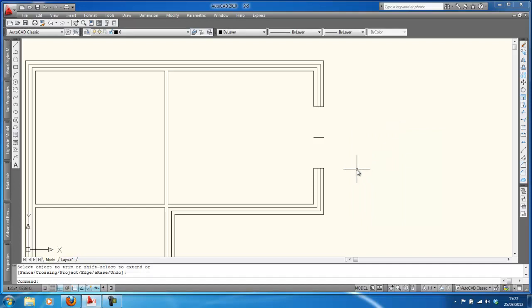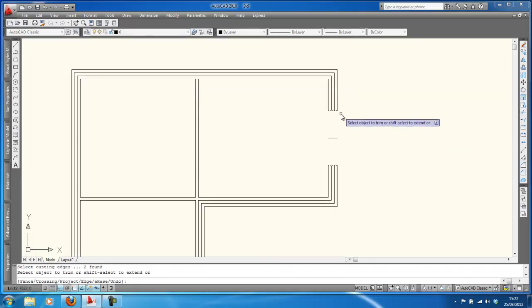Now, the other thing that you need to understand is that when you select these slicing knives, and there I have selected them, those knives carry on right the way through, even though they are not visible, because we've chosen extend and extend. In effect, they're cutting through all through here.